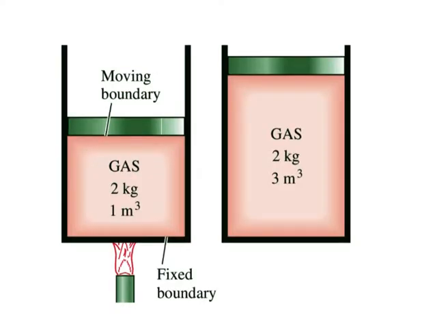Control volumes. Consider the piston cylinder device shown here. Let us say that we would like to find out what happens to the enclosed gas when it is heated. Since we are focusing our attention on the gas, it is our system. The inner surfaces of the piston and the cylinder form the boundary, and since no mass is crossing this boundary, it is a closed system. Notice that energy may cross the boundary and part of the boundary may move. Everything outside the gas, including the piston and the cylinder, is the surroundings.